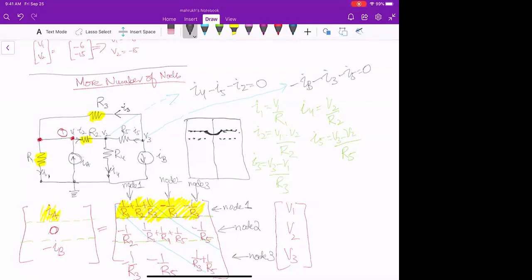And if you are thinking that entering currents are negative, keep that sign convention here. When I was writing these node equations or KCL, normally I take entering current as positive and leaving currents as negative. If you see at node 2, I put leaving currents as positive and entering current as negative. It doesn't matter for that particular equation because you are equating it to 0 and your signs will eventually be fine. But just keep that in mind: keep following the same convention for that particular equation.